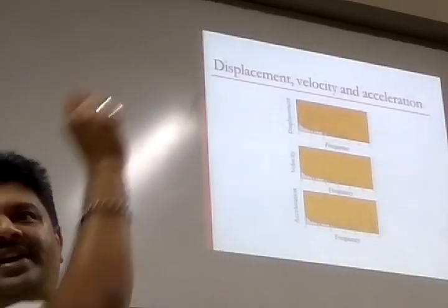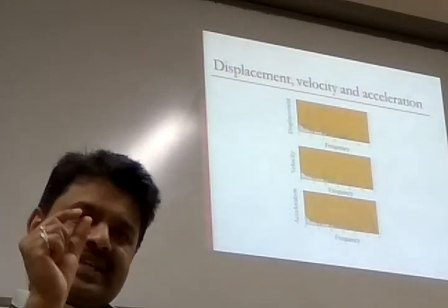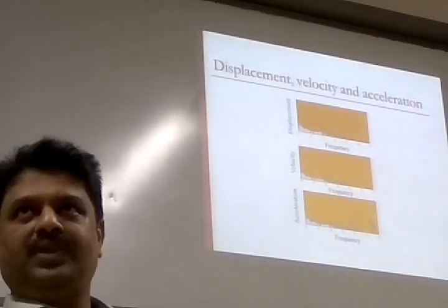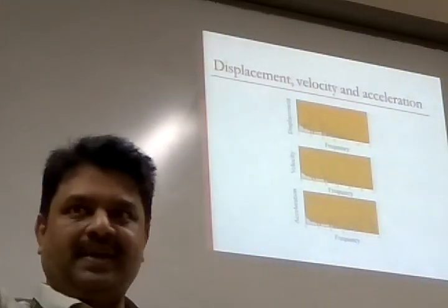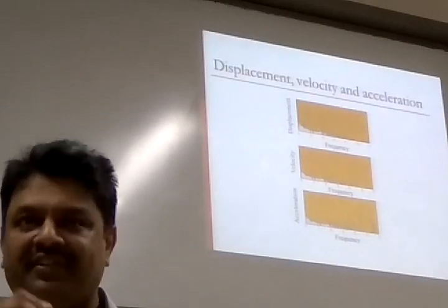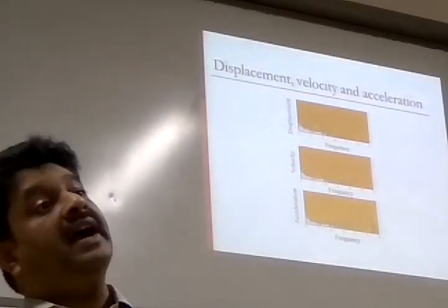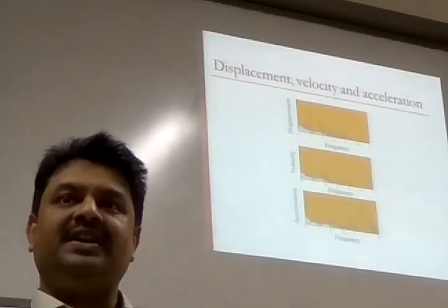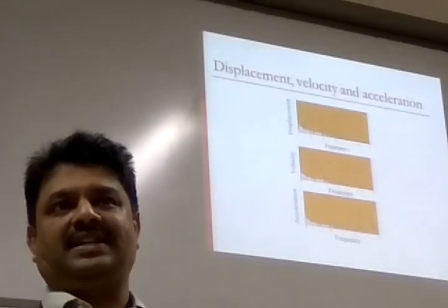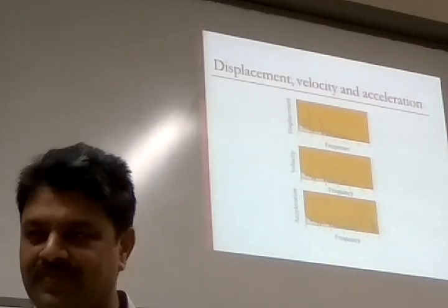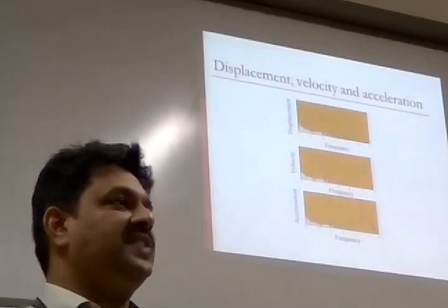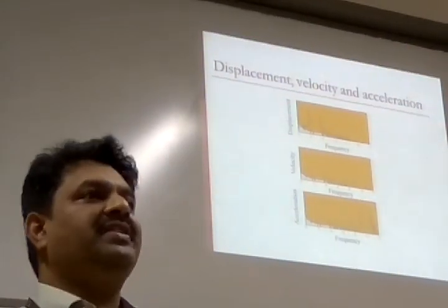Also, if you put an accelerometer and take the signal, the signal will be different from a new fan or a fault-free old fan of the same age. This will have different vibration characteristics. Normally, that variation will be in the high frequency signal. So, we are interested in change in the high frequency signal.